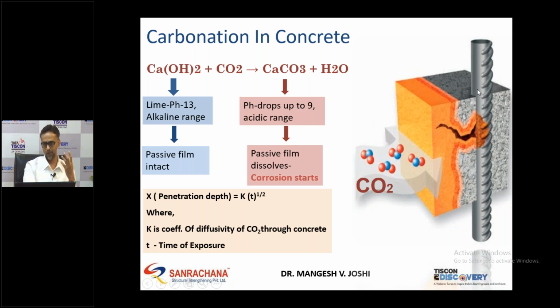So by the time the corrosion reaches the steel, you will have a usable life of around 40 years. So that's the minimum we expect, and that's how concrete protects the steel from getting corroded. But if your concrete is porous, naturally the rate of carbonation will be more and you can expect early corrosion.